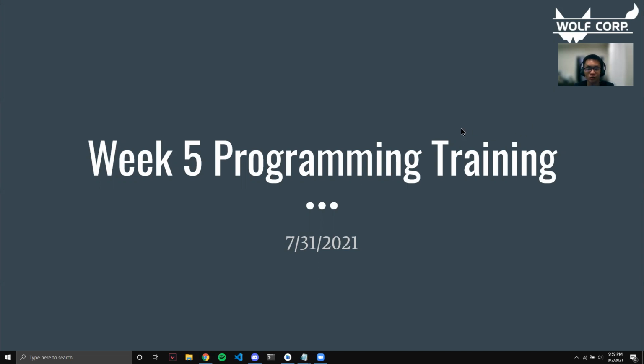So this week is week 5. We'll be moving away from driving by time, looking more into encoders, and hopefully also introducing gyro and PID, but mostly encoders. Next week, hopefully, we can implement gyro with PID. For encoders, we don't really need that much PID. There is tuning for the PID, but it's mostly good enough.